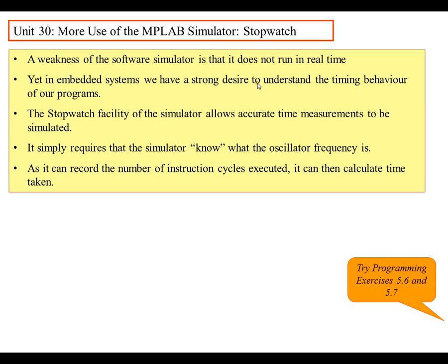If you let the processor go at its full speed, you're not going to be able to see the LED blink, because the microprocessor is so much faster than your eyeball. Your eye can only see things change about 30 times per second, but the microprocessor, for a 1 megahertz clock, can change every 1 microsecond. And we certainly can't see that.